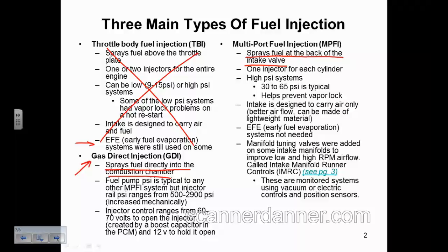I've read a lot over the years. I remember reading my first article on GDI, like in 2000, and what sticks in my head is that article said we had the ability with GDI to run 40-to-1 air-fuel ratios at certain times. But to be able to do that, they had to run a huge amount of EGR gas to make that happen, and the issue at the time was sulfur in the fuels, and we didn't have the right kind of fuel to run this.